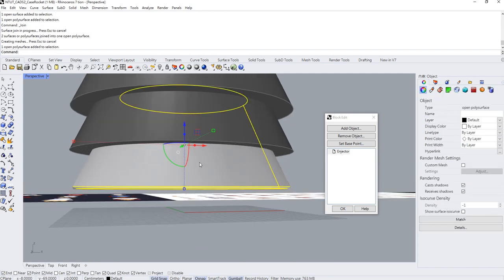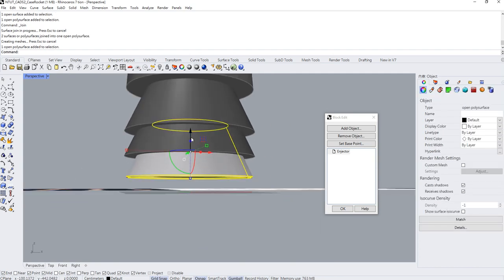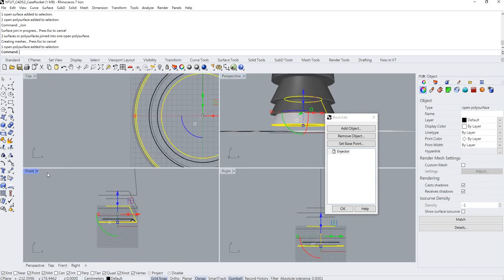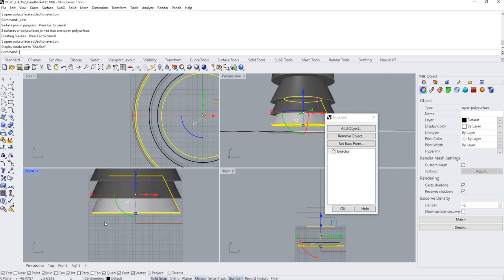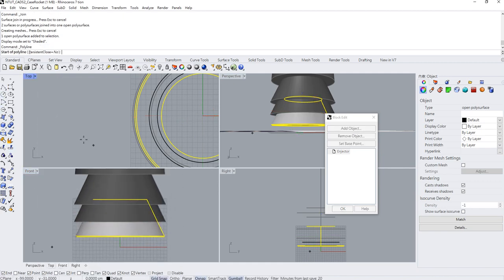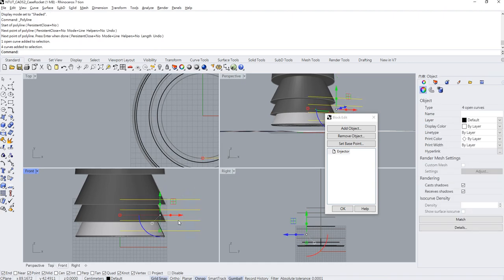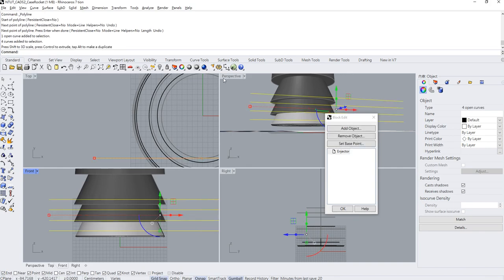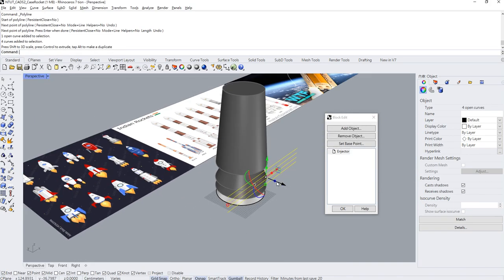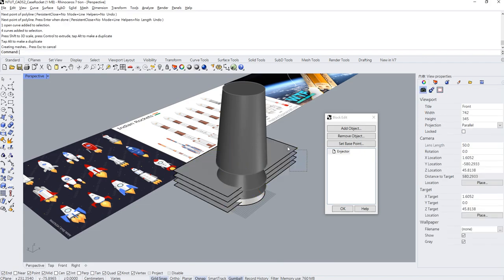For the rest of the part, the thing I'm going to do is create some carving edge right here. Just like what we did before, let's go to the front view, shading mode, and probably using polyline draw one curve and move this one down. Negative 15, 15, 15. So now we have three curves. Make them longer and extrude the surface.